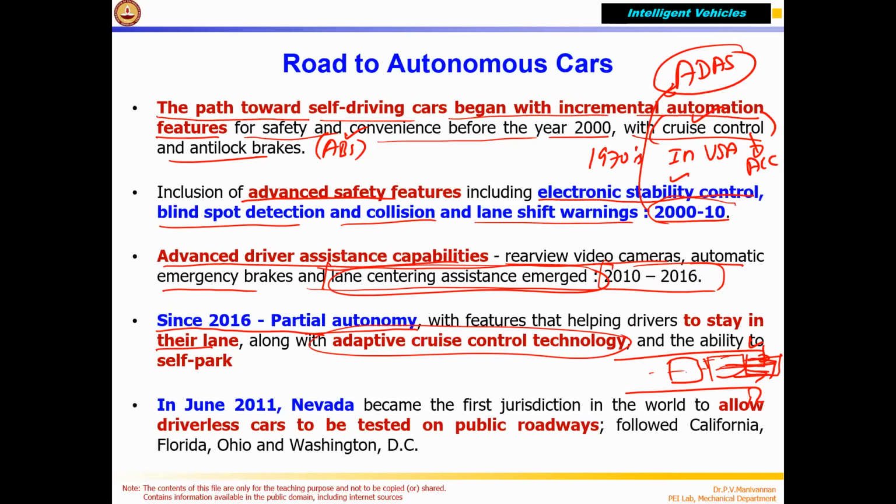But if the vehicle in front applies sudden brake, your vehicle will go and hit. But in adaptive cruise control, there's a radar which is going to watch the distance between you and the vehicle in front of you. And if the distance becomes lesser and lesser, the speed will reduce. Because you will follow the speed of the vehicle in front of you. Your vehicle speed will depend upon the speed of the vehicle in front of you. That is controlled using radar. Correct? Radar or lidar sensor, which is mounted in front of your vehicle, which measures.